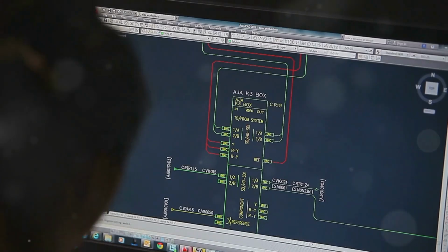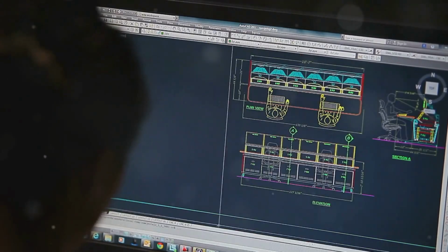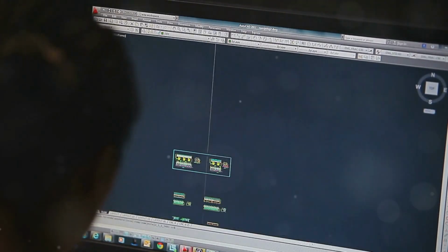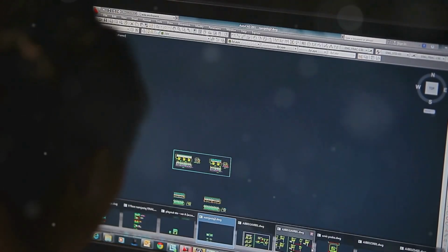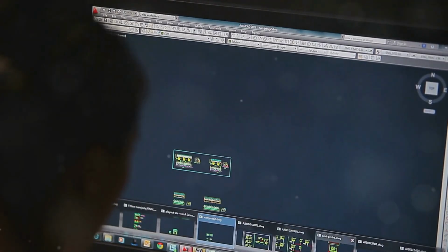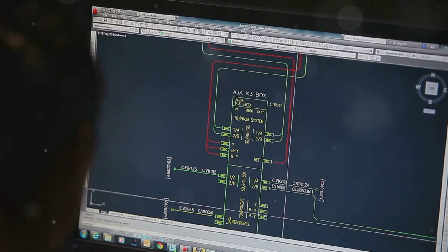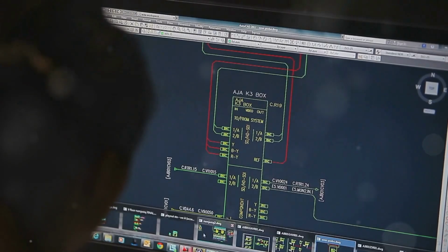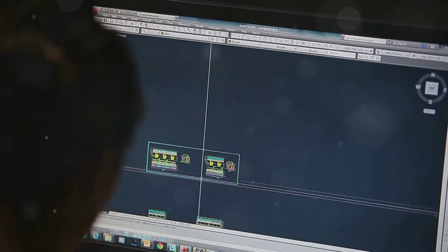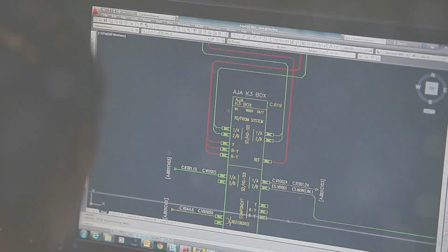Fluent mapping panels. This workflow provides a streamlined approach for transferring data between ANSYS Fluent and ANSYS Mechanical within the Workbench environment. It simplifies the data exchange process, making it easier to set up and manage FSI simulations.